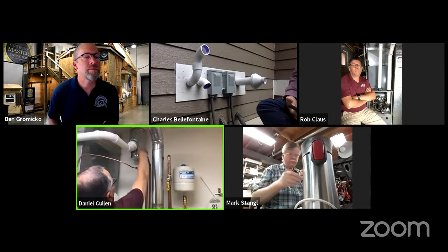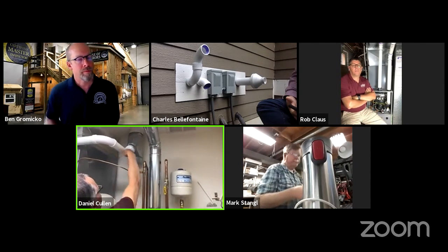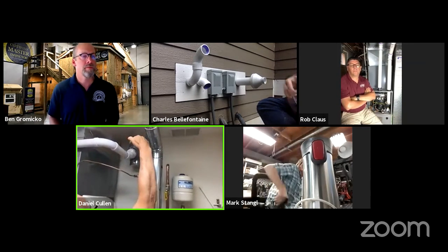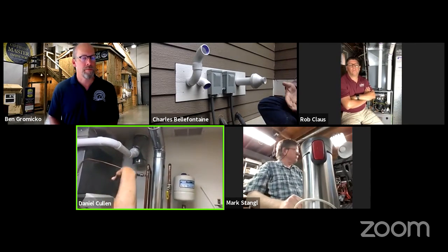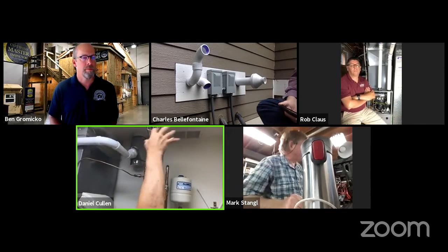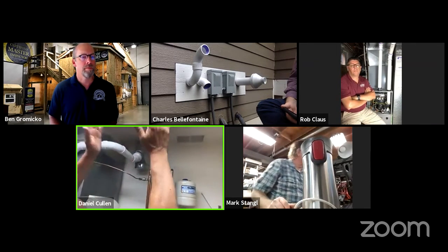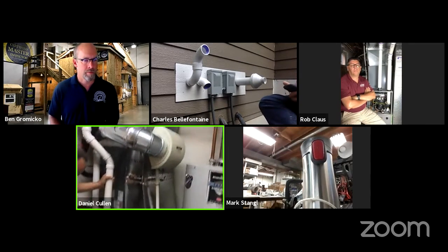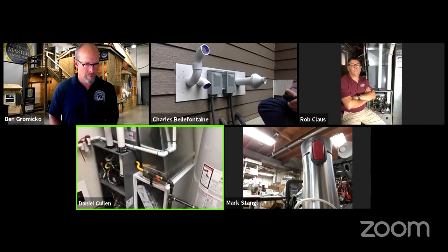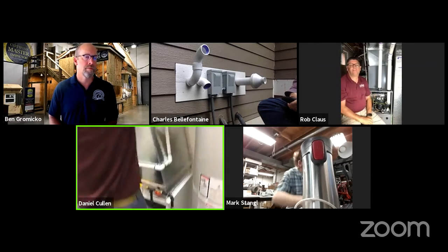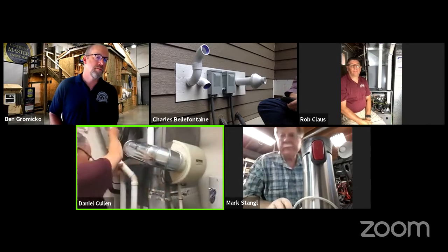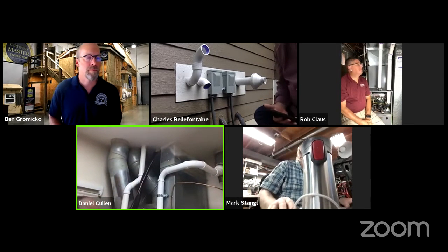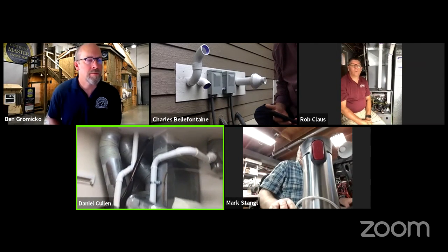We added a Y here and then tapped in for combustion air. So this just goes up above the insulation layer and it pulls our combustion air from the attic, not from outside. From the attic, which is huge and probably 14 feet tall at the peak, and supplies our combustion air for our sealed combustion furnace. The vent pipe goes out here up through a roof-mounted, neoprene roof jack.